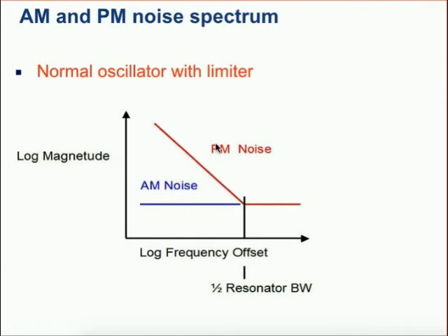So we can consider superposition here. What's happening is the oscillator is running, and a very narrow bandwidth, as we've described, is being amplified up to limit level, but actually the frequency that bandwidth is centered on is being modulated by flicker noise, but it doesn't actually upset the fact that there is this narrow bandwidth.